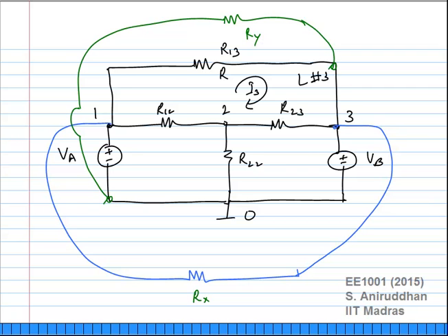Now do you see how if you start drawing non-planar circuits, it's actually very difficult to visualize the loops that are part of this. If I were just writing KCL at these nodes, I know exactly what these connections are. It is much easier to visualize it. That is the only difference. You can always write KVL for all possible loops, even for non-planar circuits. It is possible to solve the set of equations. So the rest of it, adding control sources and so on, you can always do this.